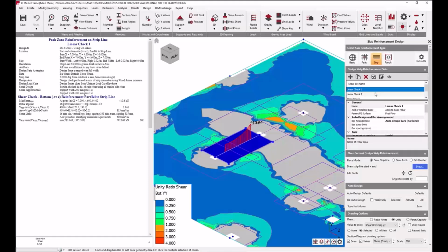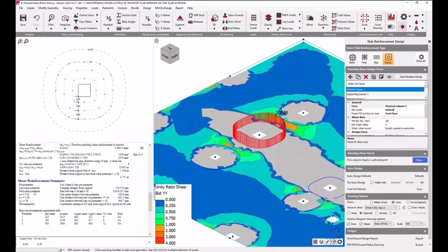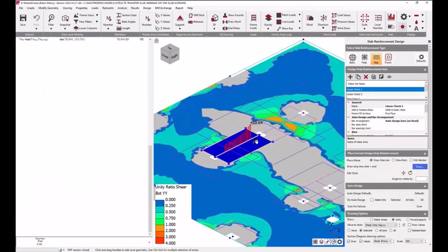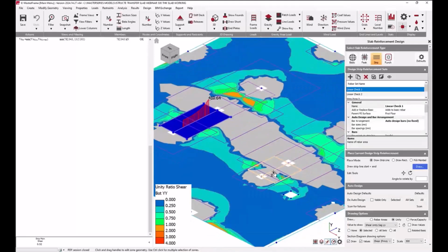The software tells you what exactly you need. So you need 16mm diameter vertical legs at 335 millimeter longitudinal and transverse spacing. And then, as I say, we can compare that to what we're getting at 2D from the column face, just for a sanity check there as well. So that'll need to be detailed manually, but if you are able to work your way through that and understand everything that the guidance is providing, you should have your linear shear checks done.